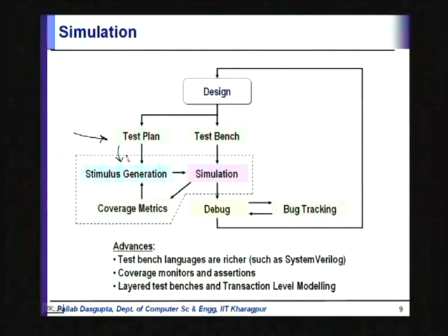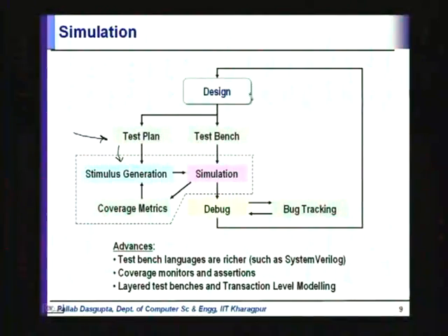You take the test plan document and code in the different tests that you will run on the design under test. Another jargon which would be useful to remember is we refer to design under test as DUT. So, when I colloquially say that we are going to drive this into the DUT, it refers to this design under test.